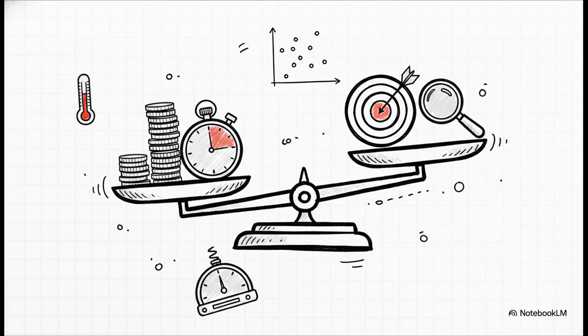The reality of measurement planning is that we are constantly having to balance the cost of the measurement against the required accuracy. Sure, you can always take more points or run the probe slower, but in manufacturing, time is quite literally money. We have to manage our uncertainty intelligently.